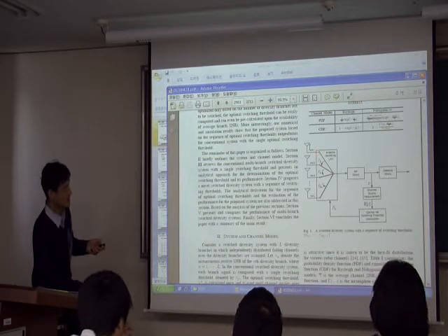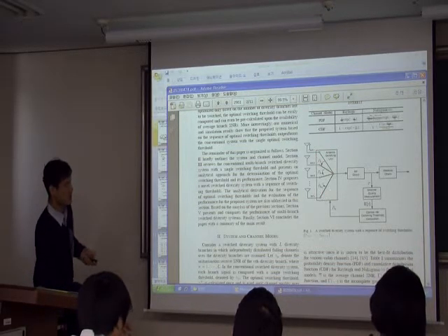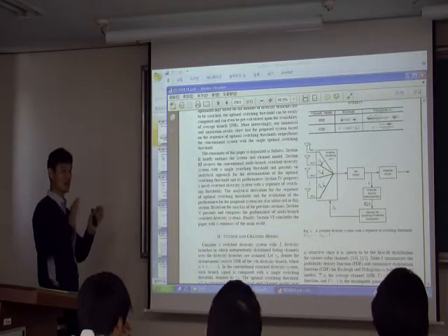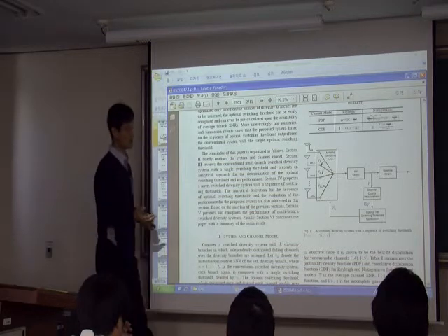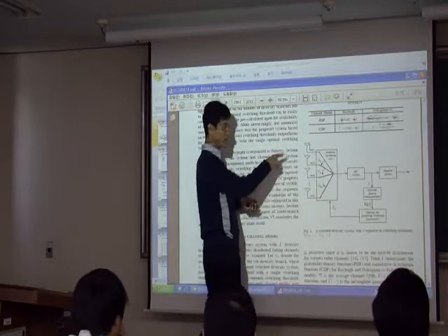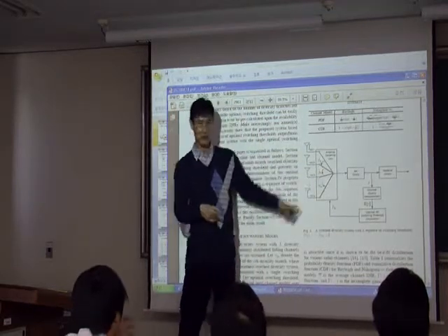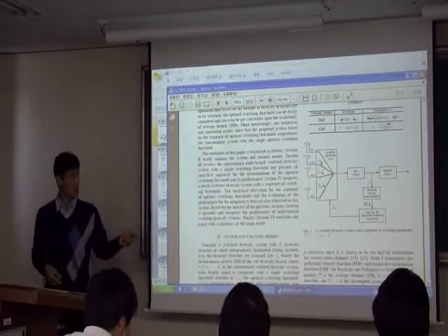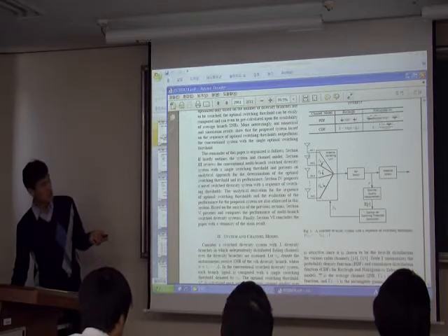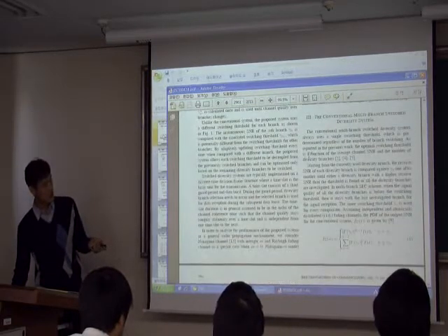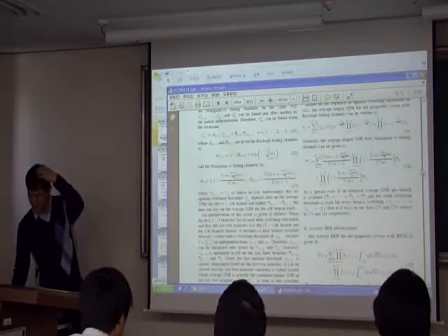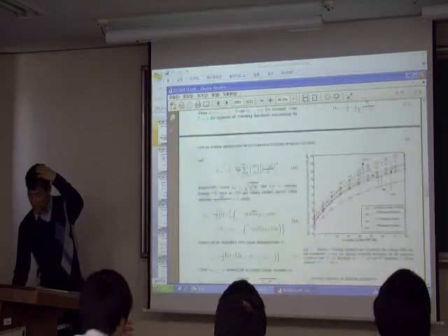The idea here is that generally in switch diversity, as long as my channel quality is good enough, I don't care and I'm not going to switch. That was the case. So for every single antenna, I'm using the same threshold. But in this case, I was trying to use a different threshold for each antenna because different antennas may have different channel statistics. That actually motivates it. Once you make such an assumption, you can bring up some simple equations, and you end up getting some performance analysis like this.